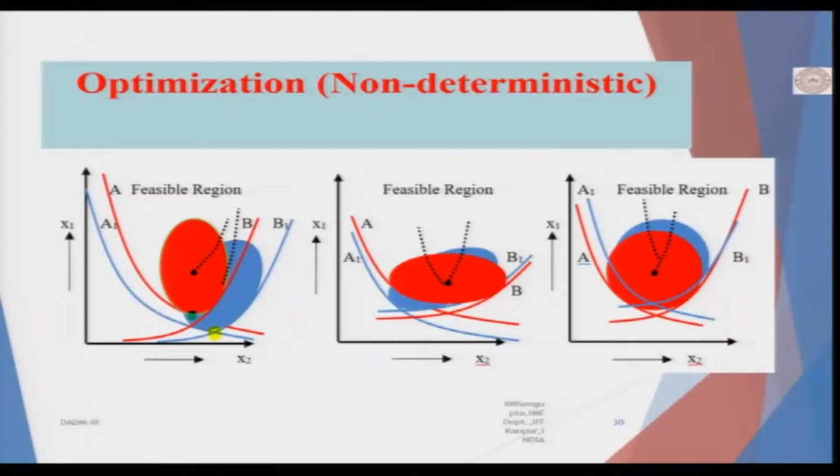Now, the third panel, which technically should have come on the left part, is when both the variances of x1 and x2 are the same and they are orthogonal. So, if they are the same, then we try to find the center of gravity for the point where again the loci would move inside the feasible region, and the overall area would be given by the level of reliability which you have. Now, remember one thing, reliability of the beta.